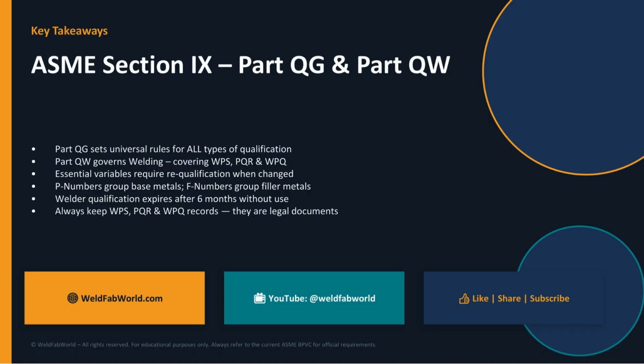Learn the system. 5. Welder qualification expires after 6 months without using a process. Keep continuity logs. 6. WPS, PQR, WPQ are legal documents. Keep them. The authorized inspector will ask for them. I genuinely hope this made ASME Section IX less intimidating, because it really is a logical document once you understand its structure.